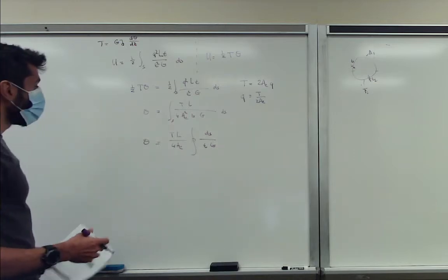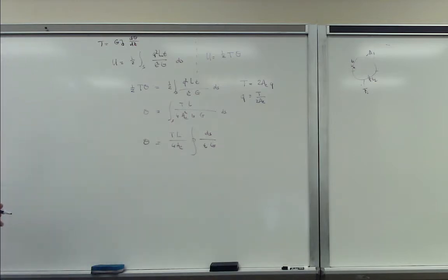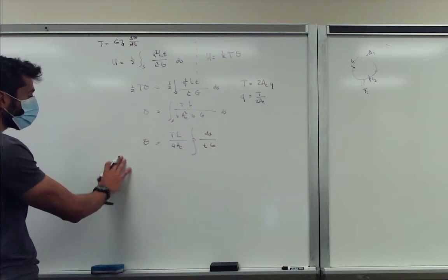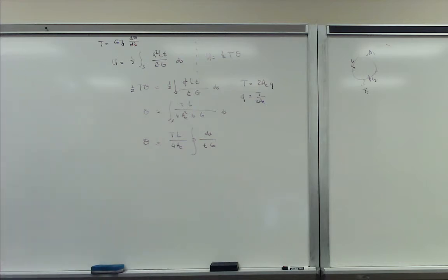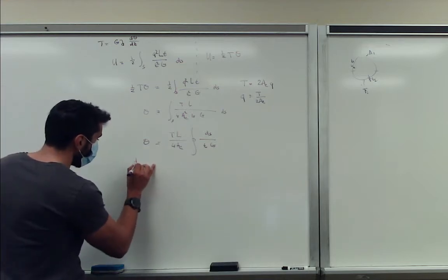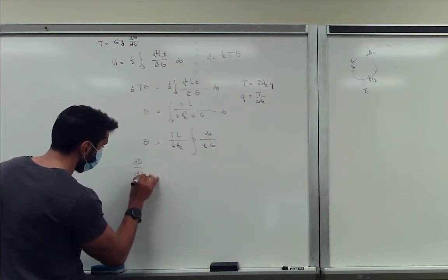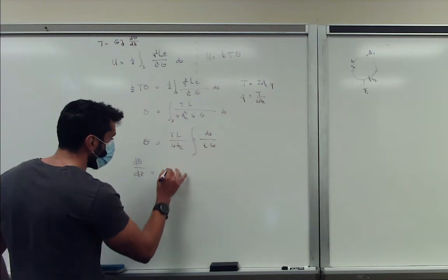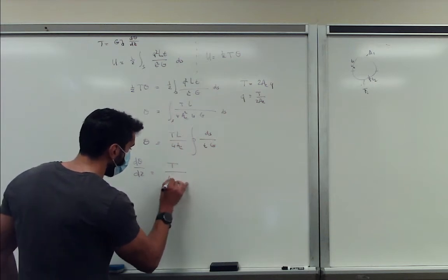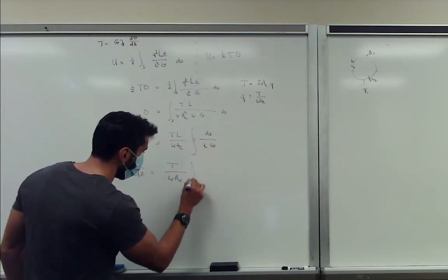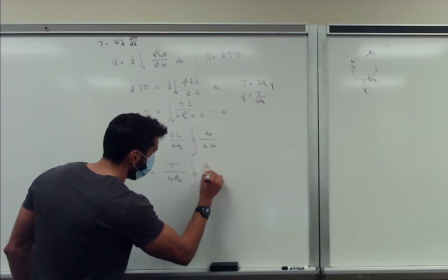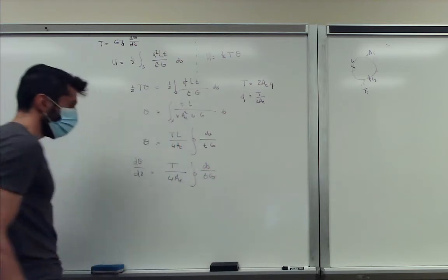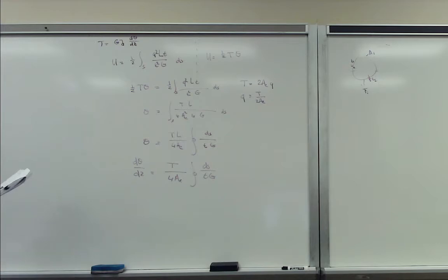And of course, in our solid sections, we said like, well, this is the twist angle, and if you want a rate of twist, that's basically the variation with respect to length. So if we do the theta dz, the rate of twist, basically what happens then, the L drops out, and your integral becomes this. And let's see what we had previously.